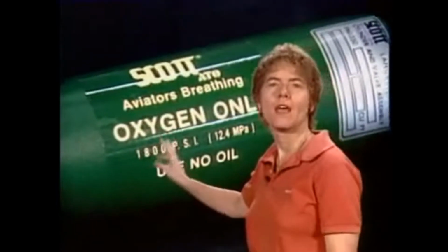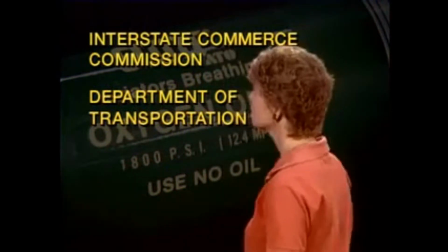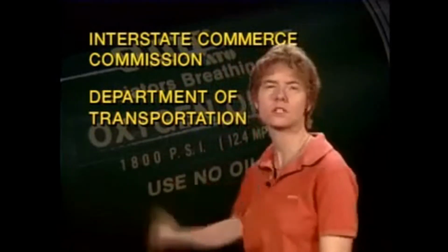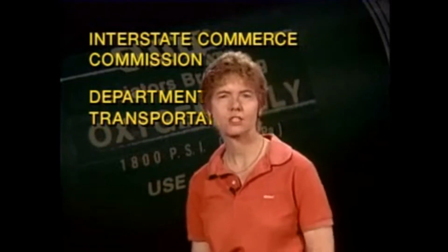Now, if you're going to install a high pressure oxygen cylinder in an airplane, that high-pressure oxygen cylinder has to meet certain specifications. And those specifications it has to meet are the ones of either the Interstate Commerce Commission or the Department of Transportation. Both the Interstate Commerce Commission and the Department of Transportation have specifications for high-pressure oxygen cylinders, and the cylinder has to meet one of those two sets of specifications.